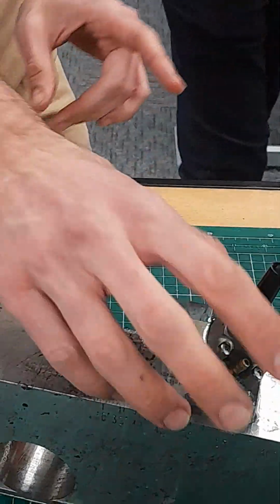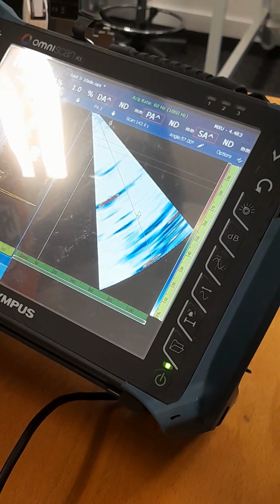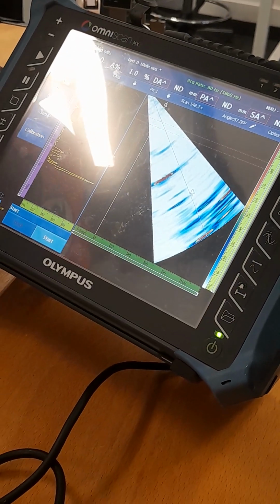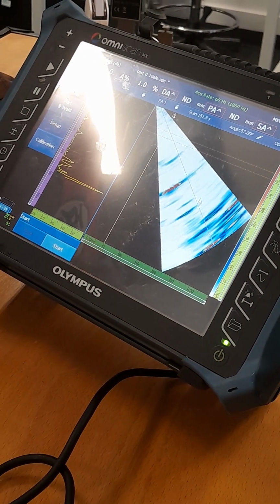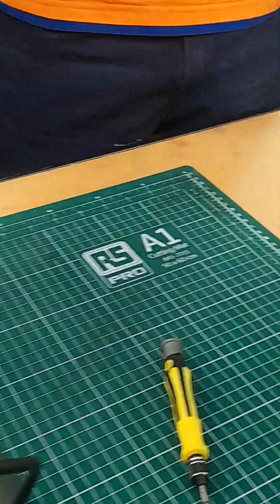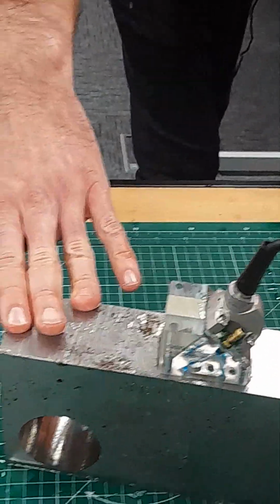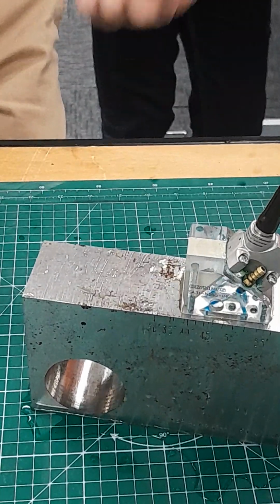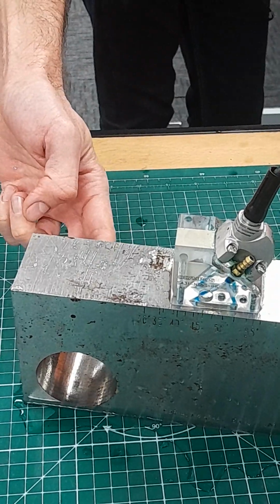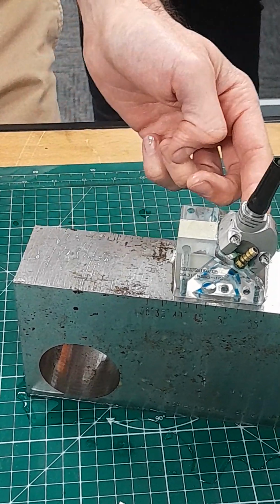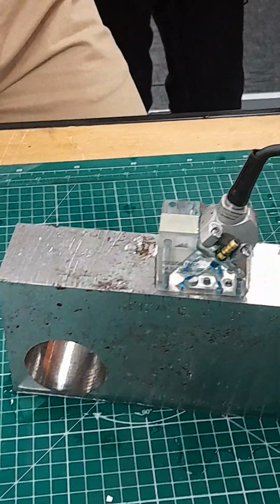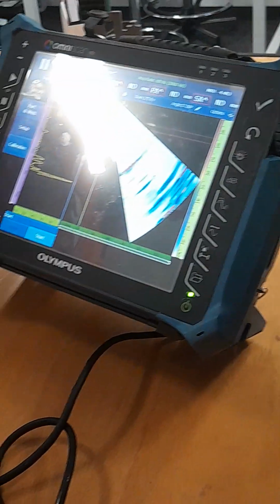You do get it, that's why it's not always trivial to deal with ultrasound, because the sound would bounce in the material. Because of the grain structure of the material, it bounces. Carbon steel is very clean, it has a very small, fine microstructure. The sound is bouncing off that, up there and back again, for example. So it's bouncing continuously.